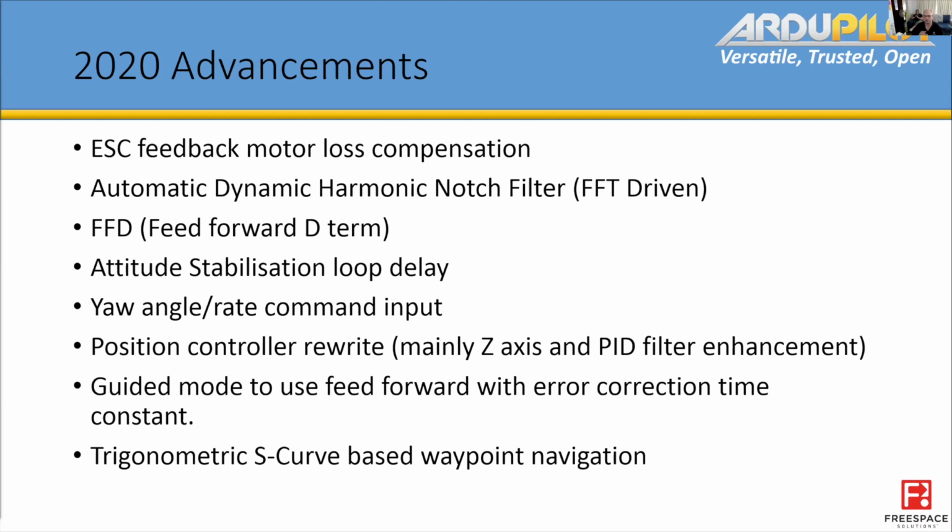Automatic dynamic harmonic notch filter, the FFT driven stuff that I was talking about earlier, that's going to be significant. You need to know what you're doing setting that at the moment with the current throttle based thing. You need to do an FFT, where this potentially allows automatic settings to work very well.